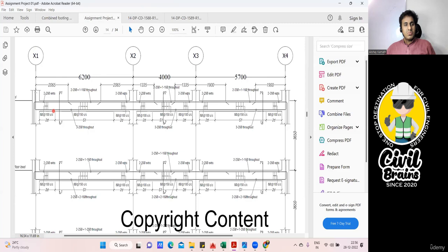So this will be a bottom straight bar. Okay. This bar will be your bottom straight bar. And what is this diameter? It is mentioned: 20 diameter 3 bar. Finish. Your bottom portion is done. You know how to prepare the BBS for this: this span, then the development length on this portion and the development length.